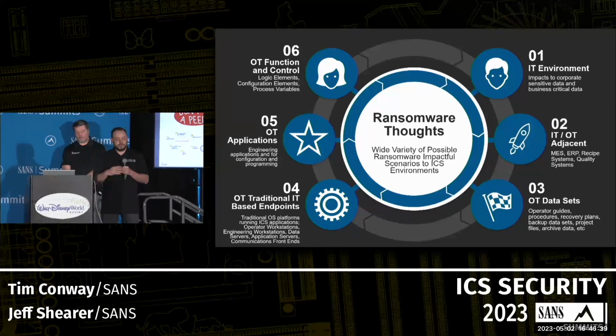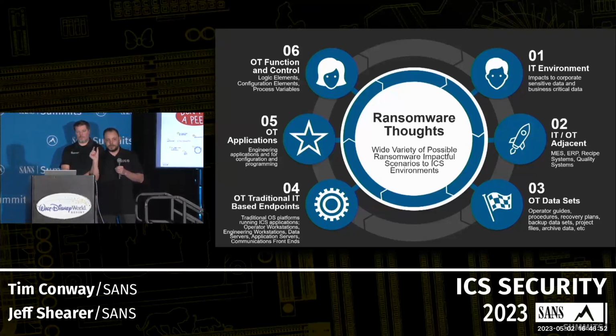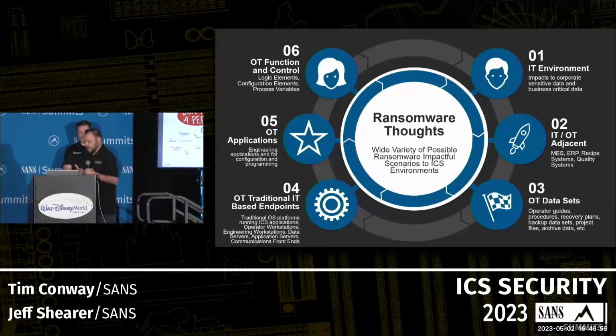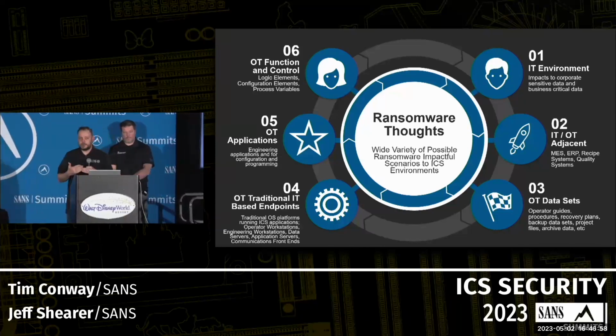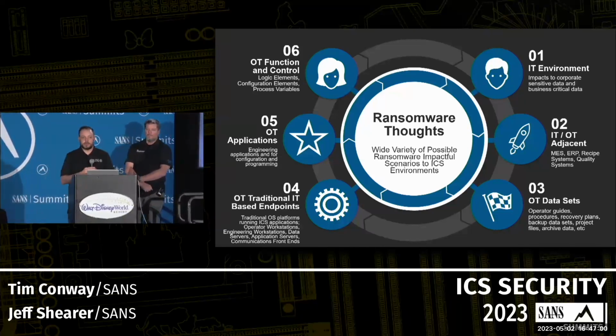So you could recover your logic, you could gain access back into your PLC, you could recommission, you could reconstitute, and then go in to look at your logic and find you can't see it, because someone locked you out of the actual logic program element. These are the things that, when you try to reconstitute that plant and bring it back up from an integrity perspective, you may find yourself in a position where you need to re-engineer and rebuild so that you can run safely. Number 5 and number 6 is really where we're going to spend our time.